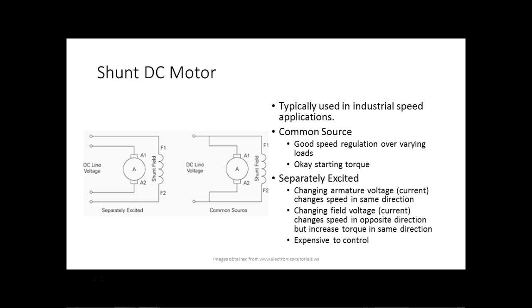Well, the motor starts up. It has very, very low opposition in the armature. We put voltage across it. But as soon as the armature starts spinning, it starts cutting this field right here, and it induces a voltage back into the armature that we refer to as a counter EMF. And what that appears to us, it appears that the resistance of the armature is going up, which is what we wanted, right? We need a real strong current to start the motor. Why?